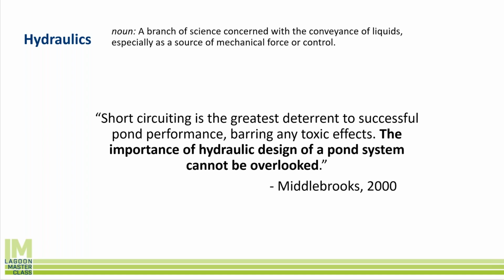So there's a quote here from Middlebrooks. He's one of the classic researchers of wastewater lagoons, probably one of the last ones that spent a lot of time researching wastewater lagoons back in 2000, and he said that short circuiting is the greatest deterrent to successful pond performance or successful lagoon performance, barring any toxic effects, right? If there's no toxicity, the next biggest problem in a wastewater lagoon system is going to be short circuiting. So we'll be spending a lot of time talking about that today.